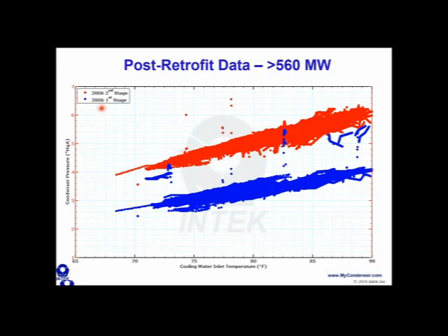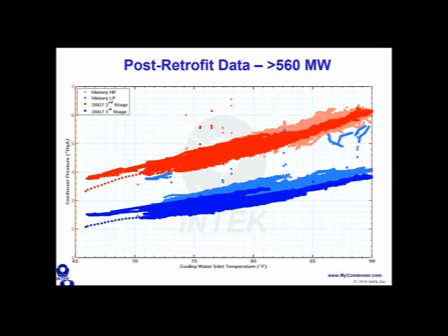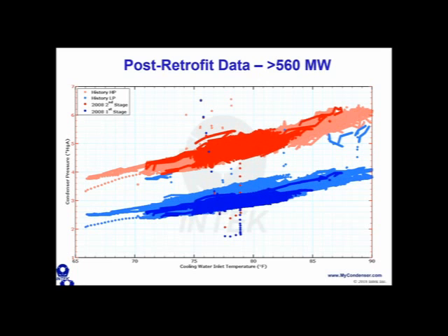Now we did the retrofit in 2010. So let's take a look at 2007 data. Here's 2007 data. There's the pressure in the HP shell, pressure in the LP shell, kind of right on top of one another. I faded into the background the 2006 data. So then we advanced to 2008. Here's 2008. So again, this is just a history of poor performance.